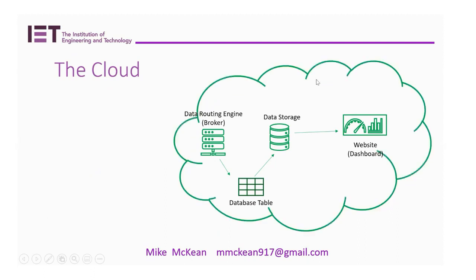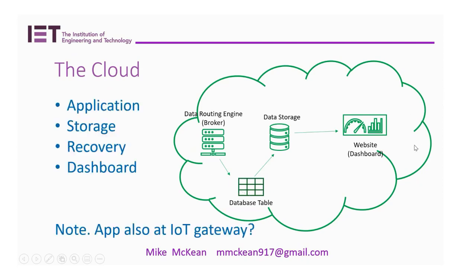Let's look at the cloud now. This could be on your premises or in AWS or Google or IBM, etc. And this is the normal IT sort of thing you would expect, but there's something else here. Remember I said the gateway usually also has a programming environment, and that's important because if you've got devices here and one of them raises an alert because there's a fire, or a temperature has exceeded a normal operating range, and that sends a message, or you poll it and the message is received by the gateway. If the LAN connection back into this environment or the cellular connection is down, then there can be a raging fire here and no one knows about it.